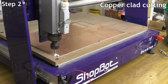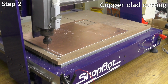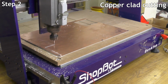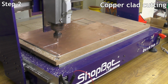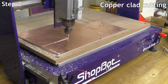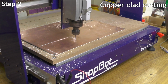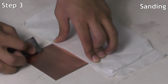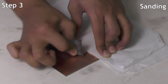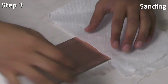Step 2. Copper clad cutting. A copper-clad laminate sheet is cut to the desired size, matching the dimensions of the PCB design. The cutting can be done in two ways, using a CNC machine or manually using a hacksaw. Step 3. Sanding. The copper-clad board surface is sanded lightly to remove any oxidation or contaminants, ensuring better adhesion of the toner during the transfer process.